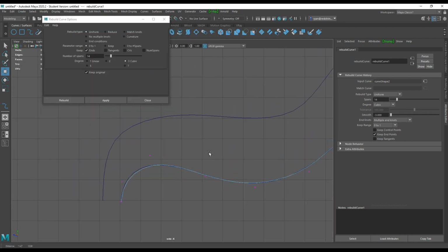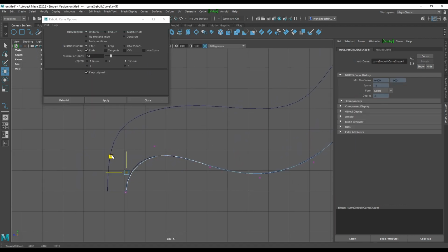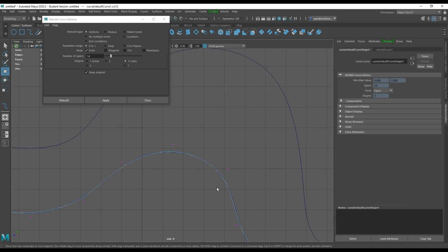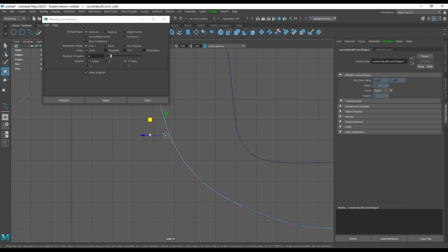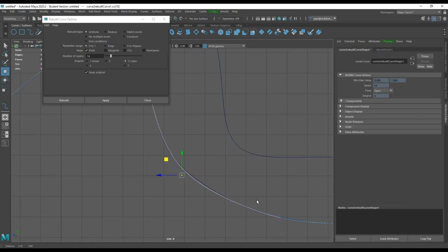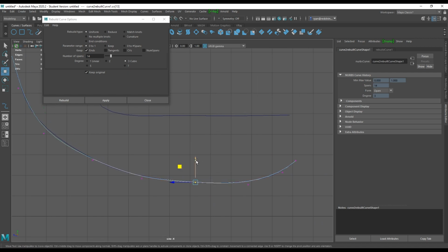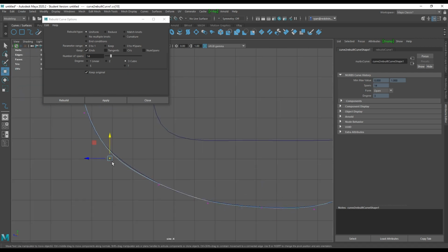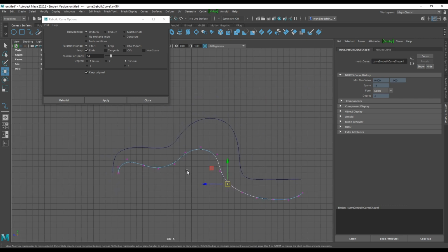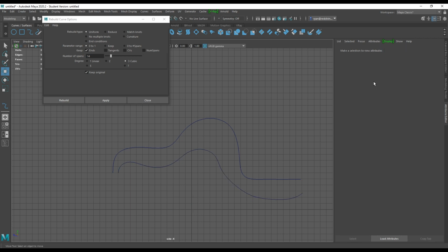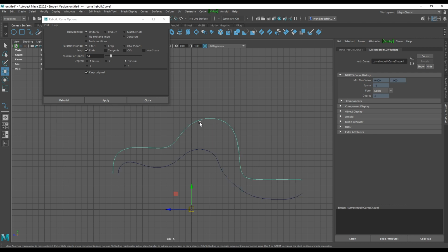I've kept the original. Now again, it's just about matching up your original curve to what you would like, because there wasn't such a big difference going from 15 to 14. There's not much corrections that we would need to do to get the curve that we want. Okay? It just depends on how much of a perfectionist you are. Object mode, I've got the 0 to 1 one, then hold on shift and just do a box selection or marquee selection over the other one. So that I select the 0 to 15 one, delete that. And now I should have two clean curves.